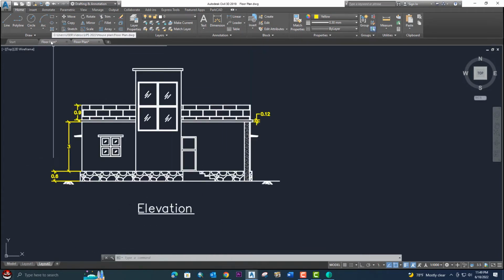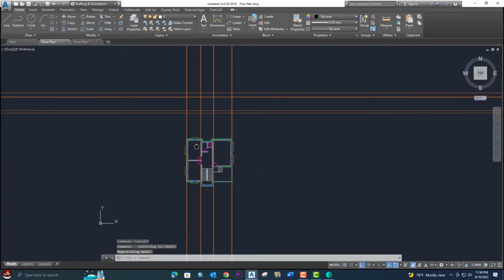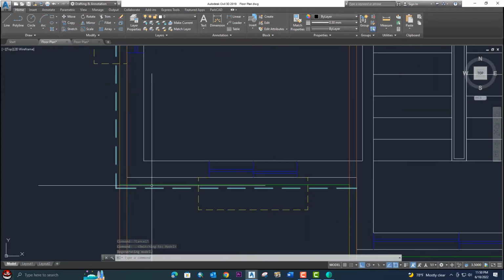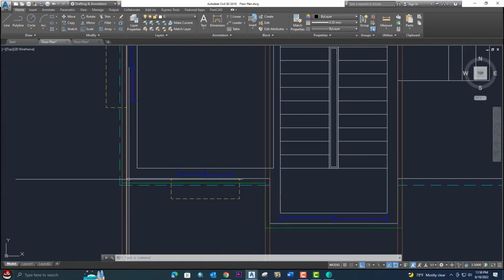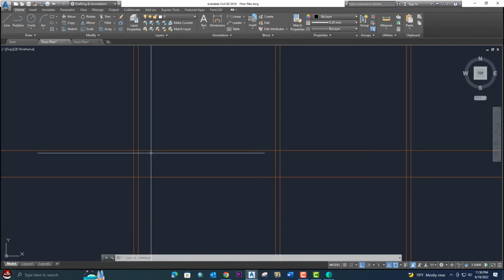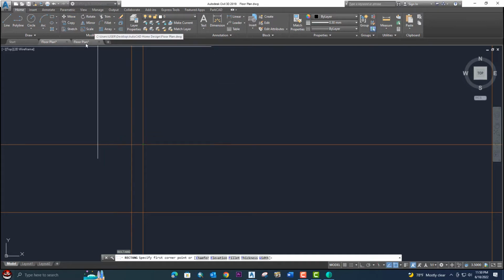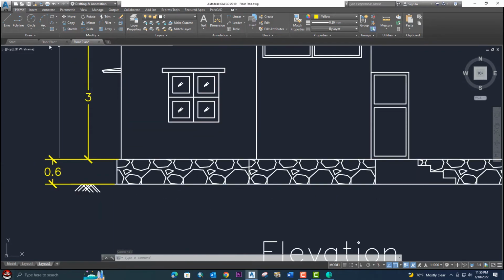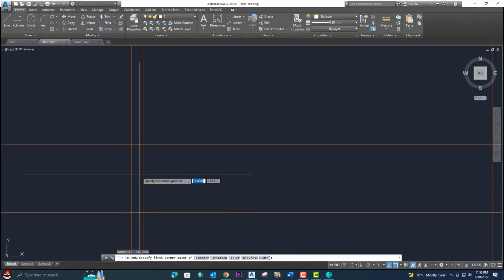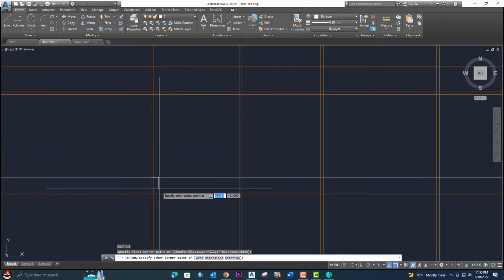Okay, so first we will go to the floor plan and model, and here, we will first connect the plinth to plinth, outer plinth and outer plinth. So we will use rectangle to draw this one. Okay, REC for rectangle, not from this, because it's a wall, so we will just take these lines. You can see here this is a little bit out, and we have also the plinth projection here, so we will use the plinth projection outer line, REC rectangle, and from here to here.